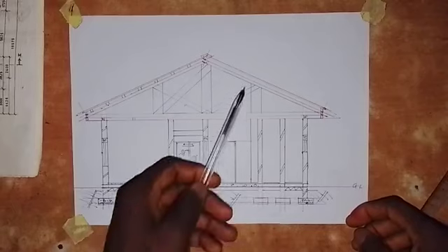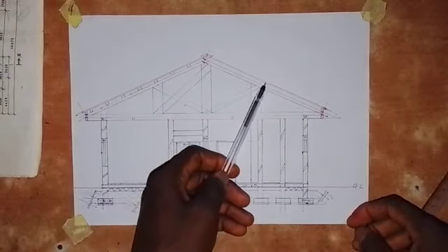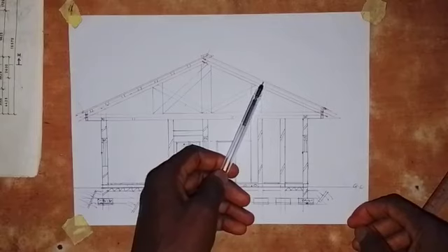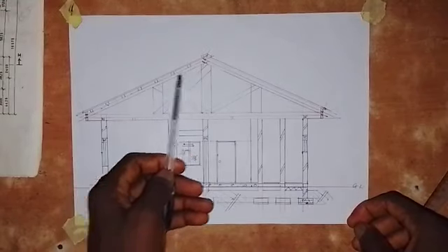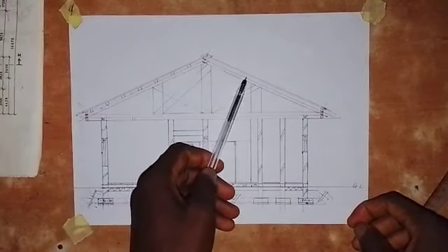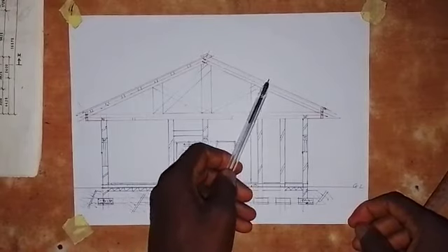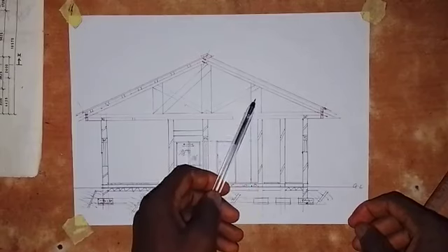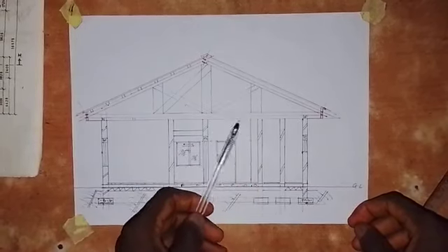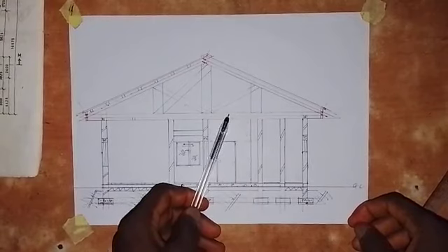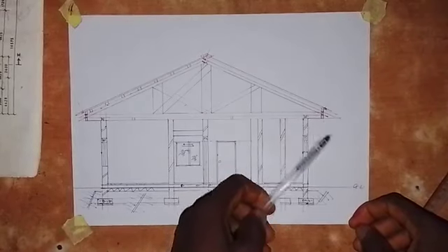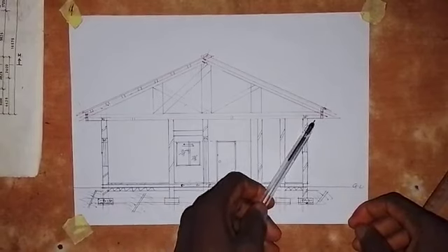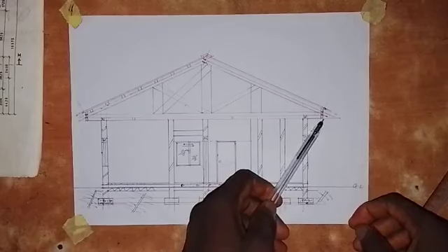And also, you can label this as roofing material or corrugated iron sheet. Then here, as I said, don't forget to put the remaining purlins. So put them here, in this space here. Then just take one of them and label it as purlin. And then this is rafter. This is king post. This is strut. And then here we have the tie beam. So we have fascia board. Then you can also write wall plate. This surface here is soffit, and the distance from here to here is eave projection.